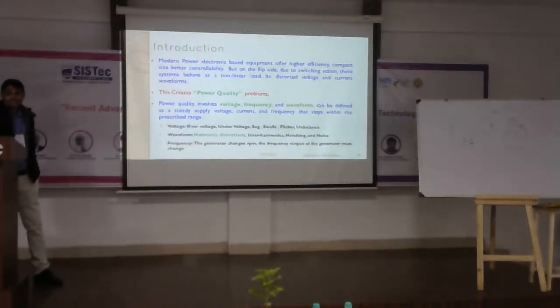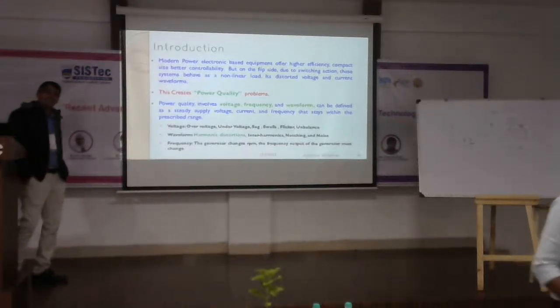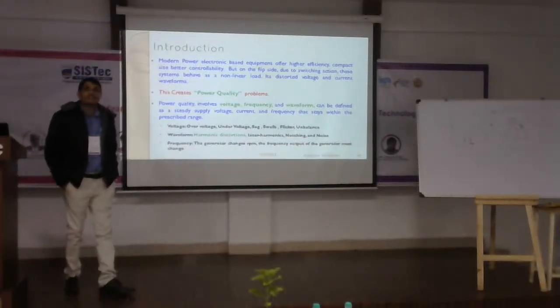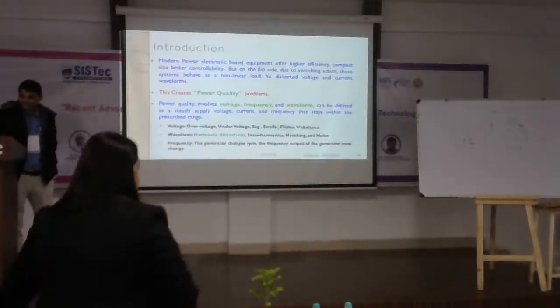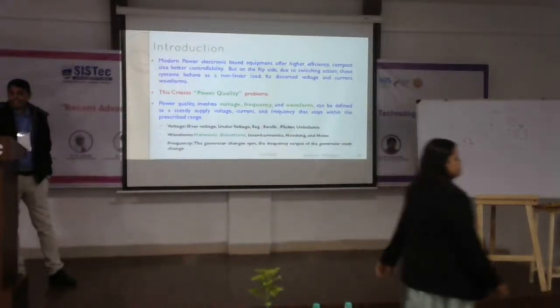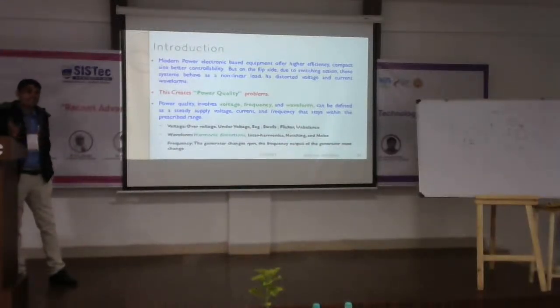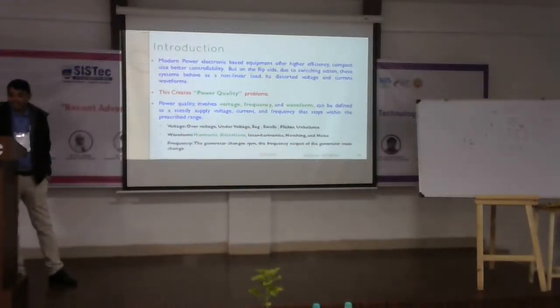And adjustable frequency AC motor drives, which means again a regulator. Uninterrupted power supply, UPS. The arc furnace, which industry uses, is a source of harmonics. Static motor starter is nothing but electronics-based circuitry. And electronic lighting ballasts, etc. So these are the sources of harmonics, and now the effects of harmonics.